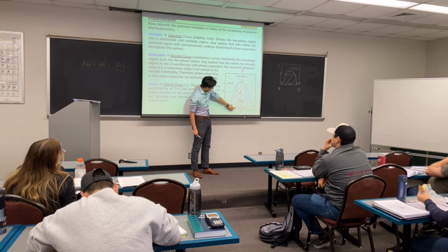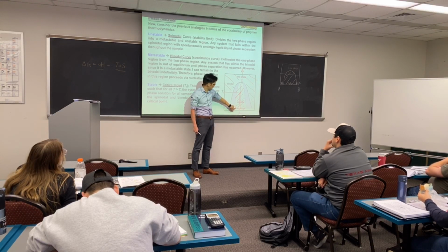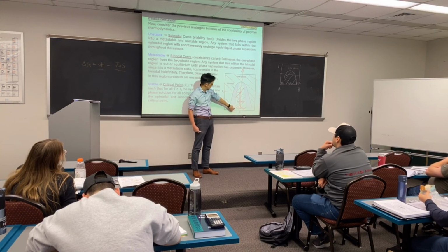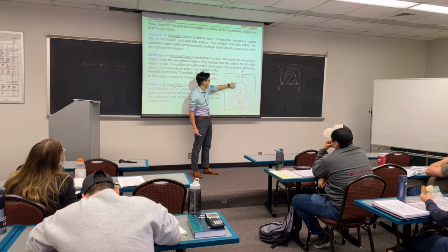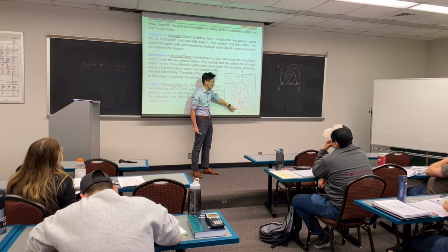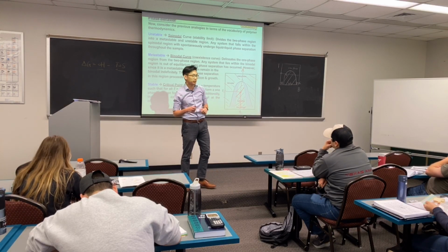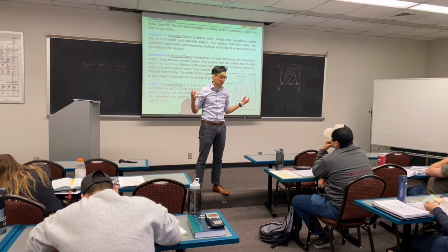Let's say you fix, how about we start from here? A 40-60 ratio. So you have 40% of B and 60% of A. You cool the system down from high temperature. At high temperature, it will be one phase, mixed. When you slowly cool down, it will start to phase separate. That goes through the metastable phase and then it will be unstable. And in the spinodal region of the phase diagram, it means it will be spontaneously phase separated into two phases.